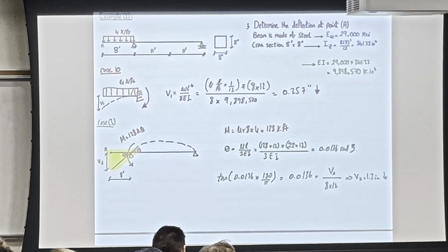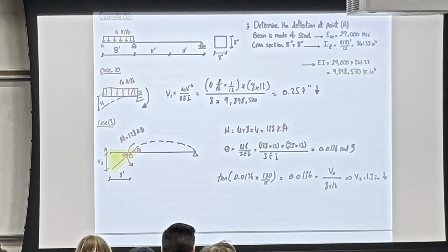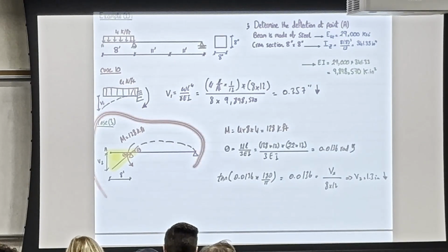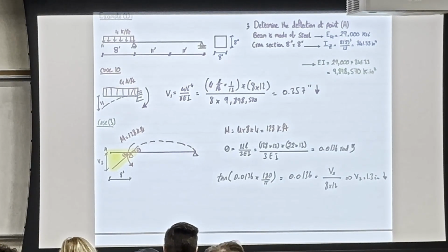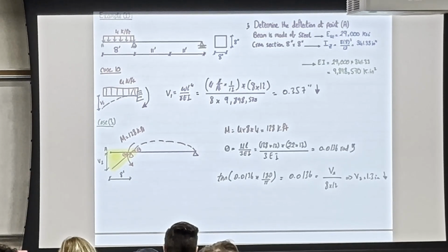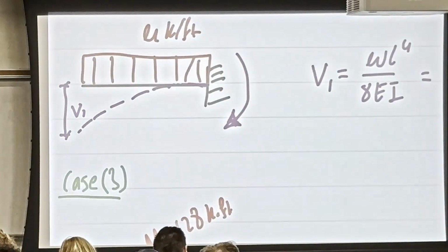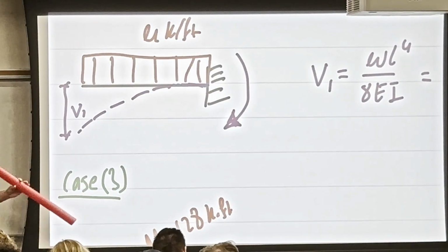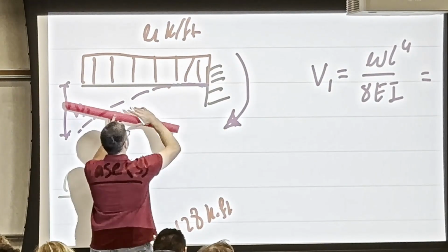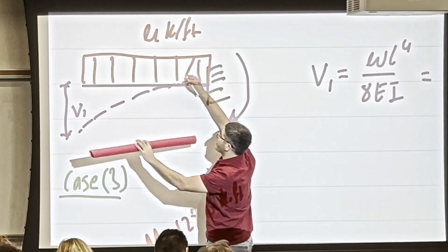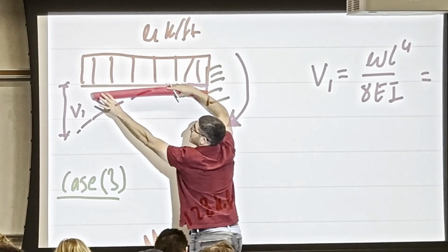Now, I do have the deflection from case 10, and the corrected deflection, I just corrected it by adding the right amount, because when I restrained, we're going to add them. What I did here, I restrained the deflection. If I'm just holding it like this, because the fixation doesn't allow any rotation here, it's going to bend a little bit.